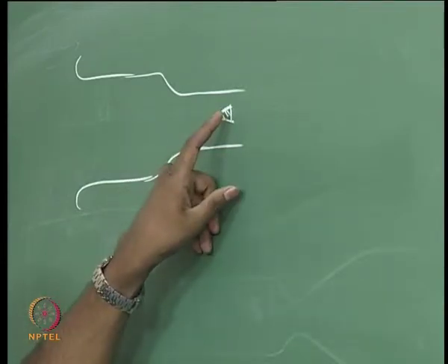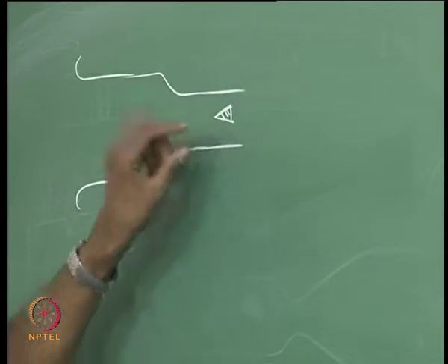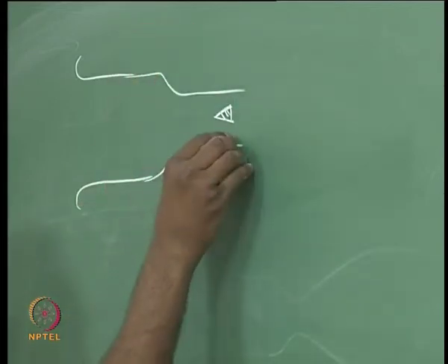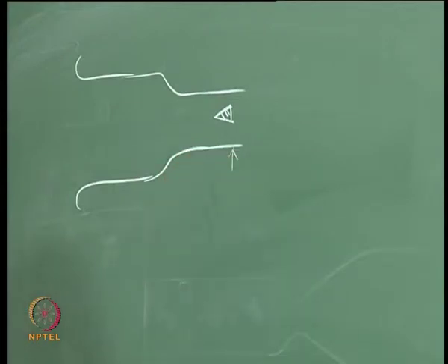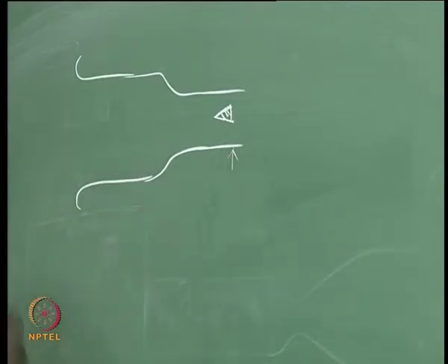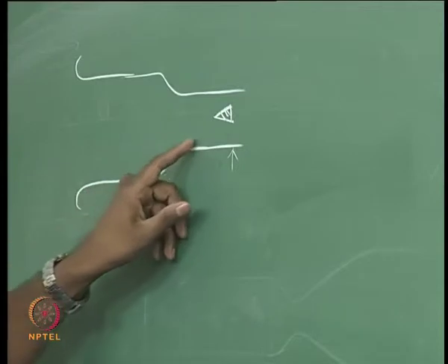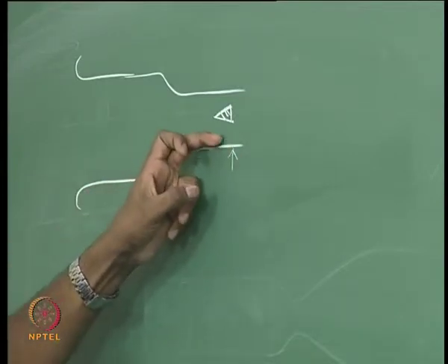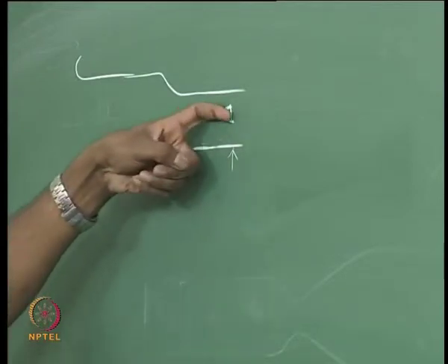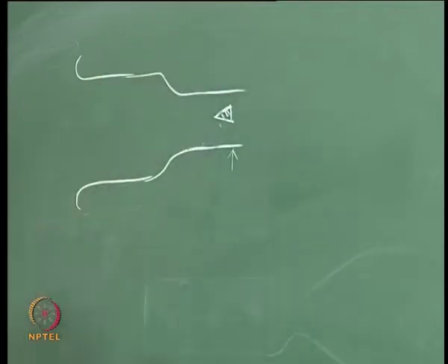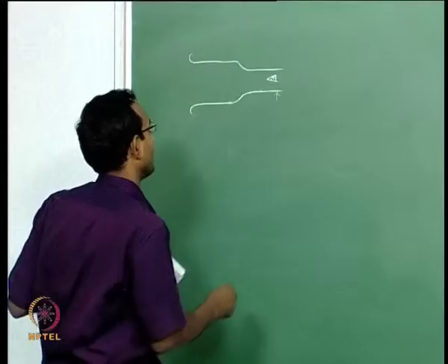If I put a model there, the area at the throat of the nozzle is only the area available for the flow around here. So the actual throat is somewhere at this location. If I think inviscid, if I think viscous, it can be even ahead of it. Okay. We said viscous effects will have boundary layer growth, and because of that the equivalent wall can be shifted a little more inside and this wall will be shifted a little more outside. So overall area available can be shrunk even more. That can also happen in there. Okay.